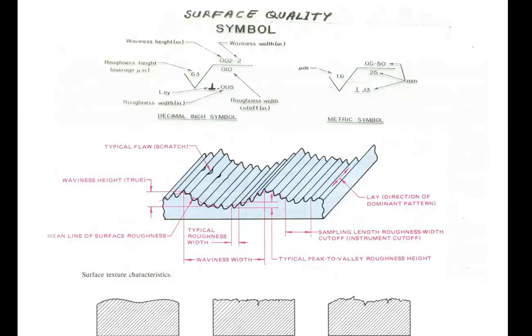is called roughness. Over the surface, since the hardness is not uniform and also the cutting tool is oscillating because of the effect of background oscillation, the value of roughness won't be a specific constant value.